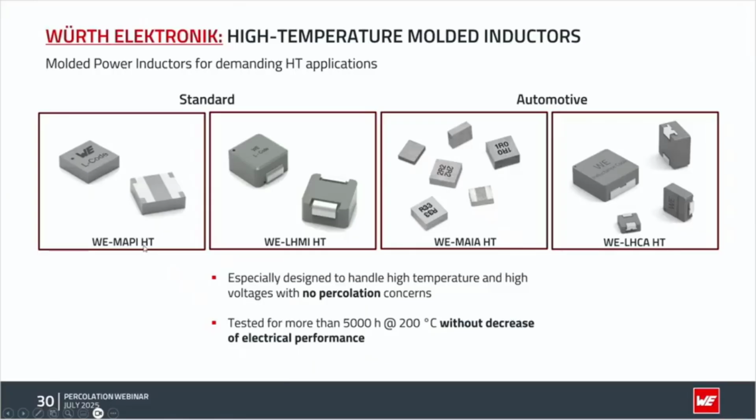So if you have an application and you're really concerned, okay, I'm going to have some peaks, for example, I saw a customer, I'm going to go a little higher in terms of saturation, 40%, 50 milliseconds, double the rated current, but that happened almost one time every hour.